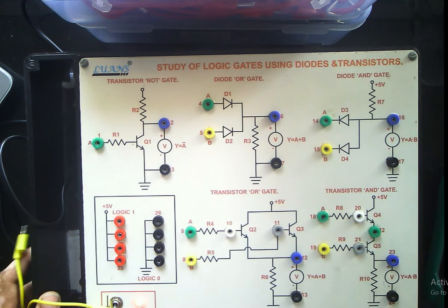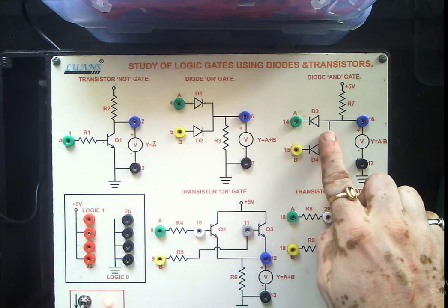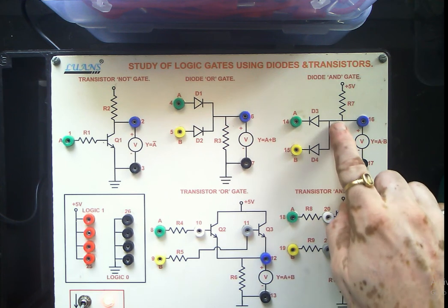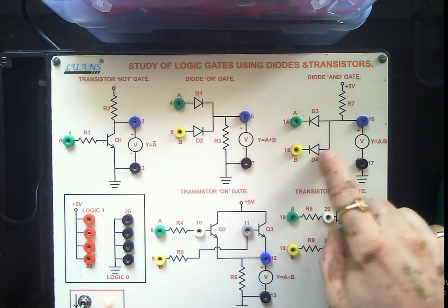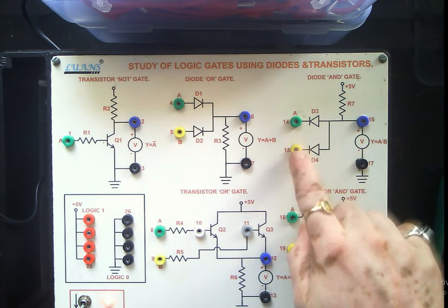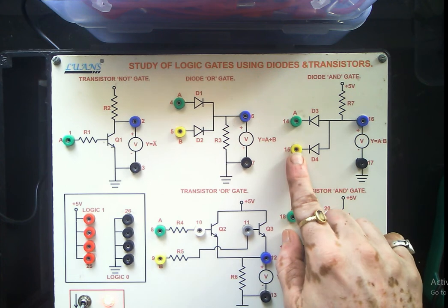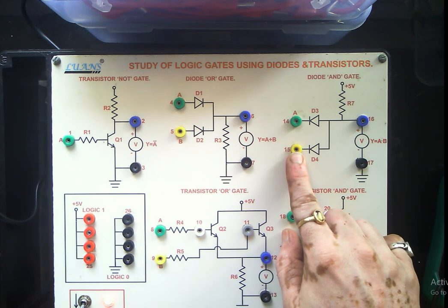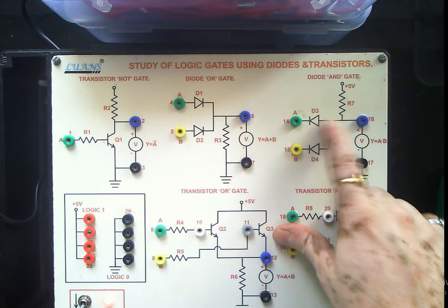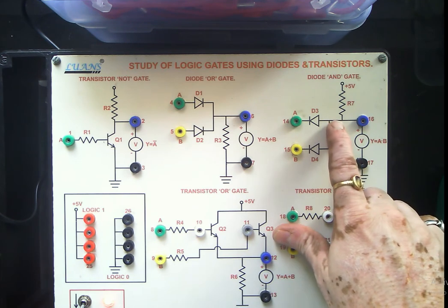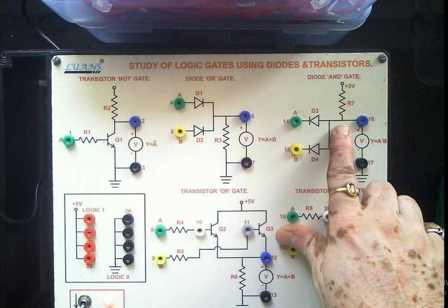Let us see how the circuit has been built. You can see here we have just done the opposite thing. We have connected the anodes together. And the cathodes are working as two terminals of the AND gate. Now you see these connected anode terminals, they are finally hooked up to 5 volt through this resistance R7.